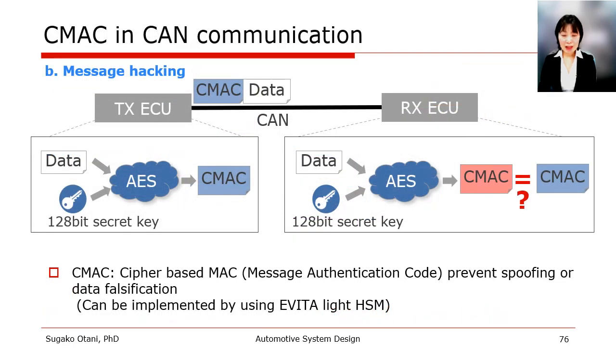We will see CMAC in CAN communication against message hacking. In order to prevent spoofing or data falsification, CMAC, cipher-based message authentication code, is used in the in-vehicle network.